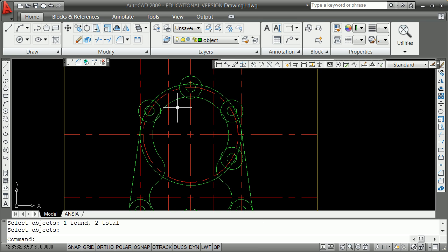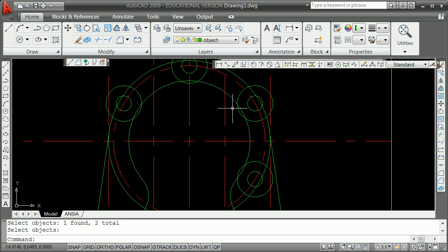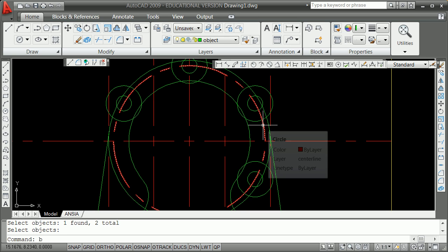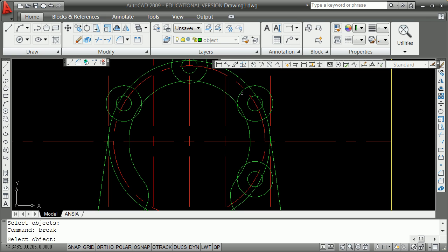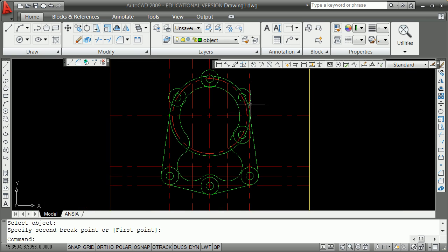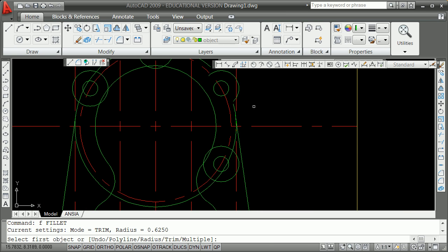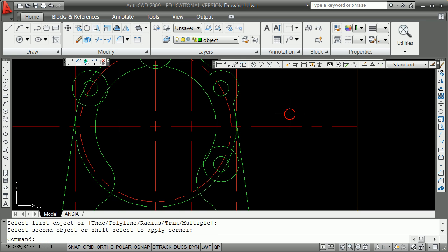I'm going to pause it, think of my final strategy, and try to get it done in 10 minutes. All right, we're getting awfully close here. We'll get it to the point where this line coming into here gets into there. We're going to break the circle going around, and then we're going to try to break the circle going around here, and we're going to try to do a fillet radius of 0.25.